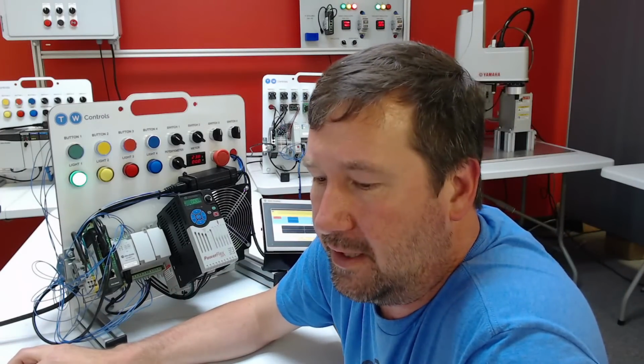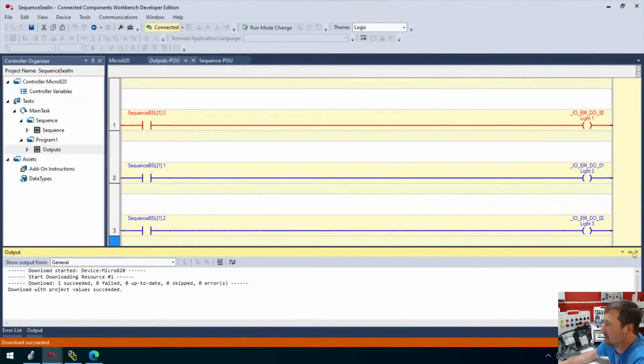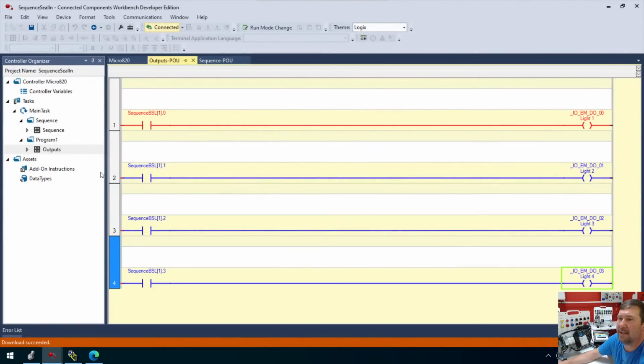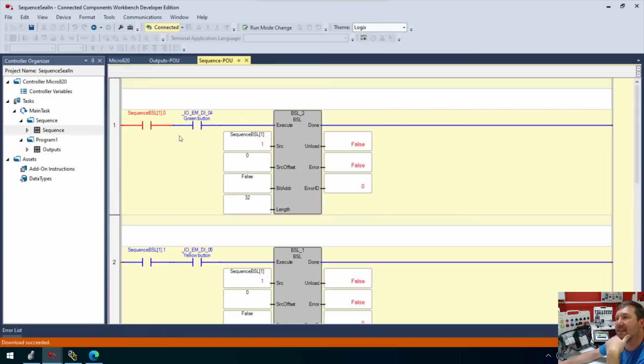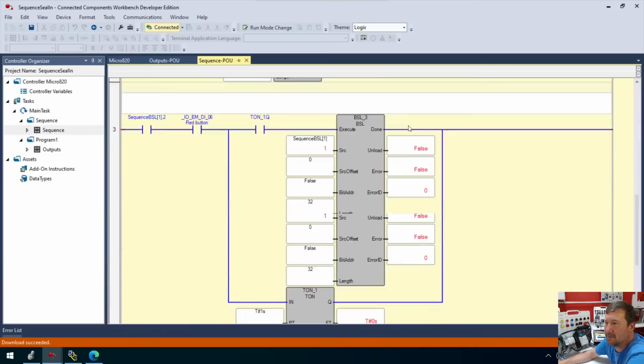And now, though, this one's going to have the same issue for me that some of the others have, if we go and look. Now, first, this is clean. I can kind of figure some of this out. But mainly, if I am not familiar with the bit shift left instruction, and I won't call it a specialty instruction to Studio 5000 or RSLogix or Allen Bradley or any of that, but it is an instruction that's not necessarily in all of them. So if you're not familiar with it at all, it can be a quick stumbling block. And so that's why I would not use this one.